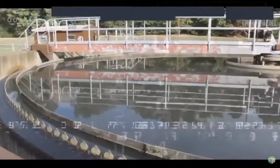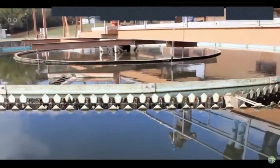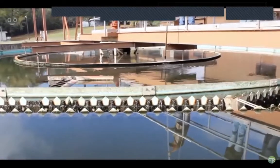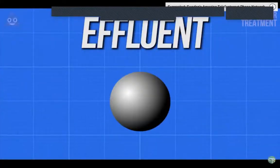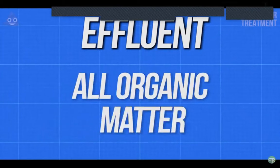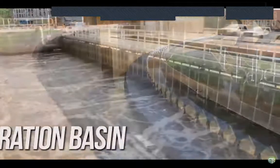In order to accomplish this, engineers will vary the size and number of primary clarifiers in accordance with the plant's permitted sewage flow rate. This ensures that at varying flow levels, solids can settle out of primary clarifiers to the correct quantities. At this step in the process, the slightly treated wastewater, which is referred to as effluent, is free of solids larger than 10 micrometers and should be all organic matter, which will be treated further. The top layer of the clarified water flows over a weir wall and into the next basin in the process, called the aeration basin.